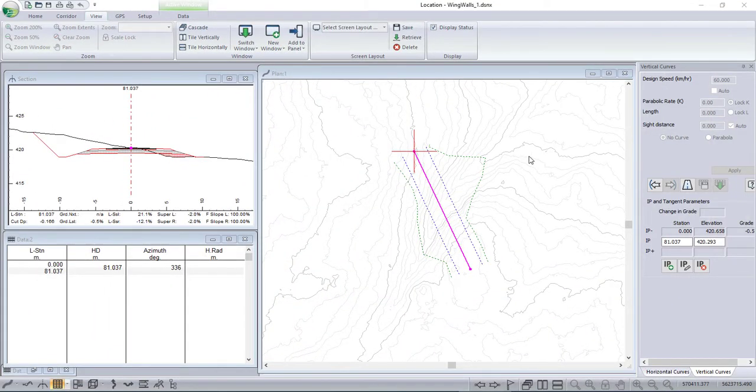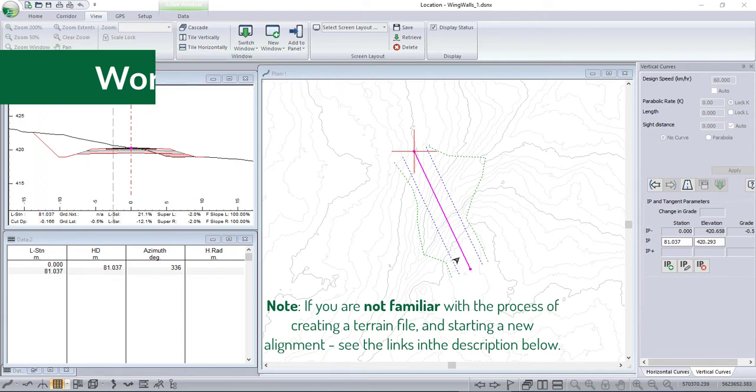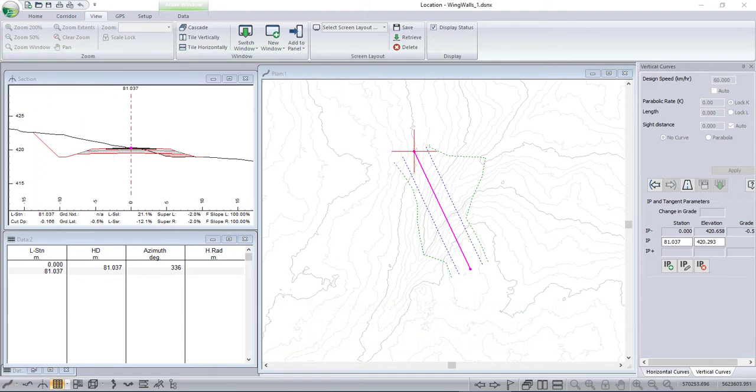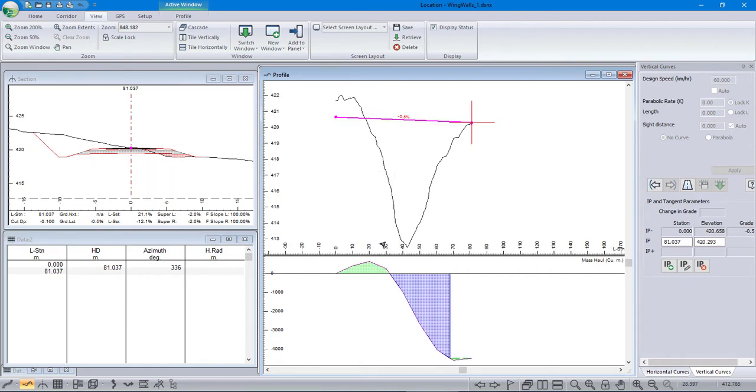We'll start the culvert design with a simple and very short alignment that crosses over a gully, and it's running from south to north, and the profile is a simple minus 0.5% grade. You can see that it crosses over this gully, which is a few meters deep. There is a natural creek at the bottom. I'm just using a stock template from the installed template table. And let's look at this in 3D.